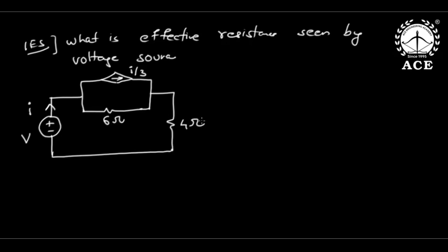So here again apply Ohm's law, because for working resistance we should not disturb anything. So this effective resistance is again simply V by I. Now see, there is a current dependent current source. Out of I by 3 went. Here directly we cannot get the answer because a dependent source is there. So I will apply Ohm's law. Out of I by 3 went, so this is automatically 2I by 3. Now 2I by 3 plus I by 3 is again I.